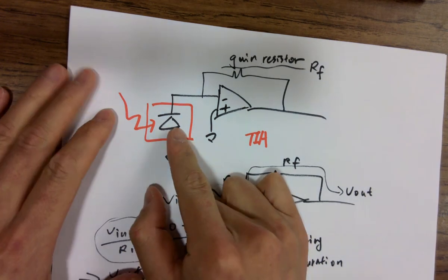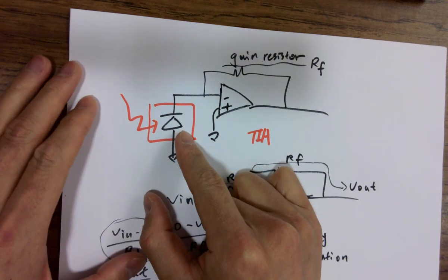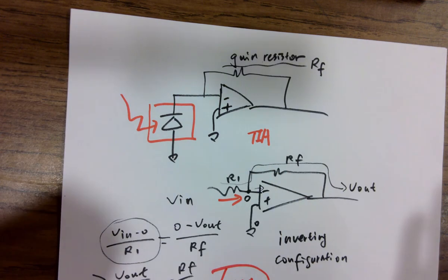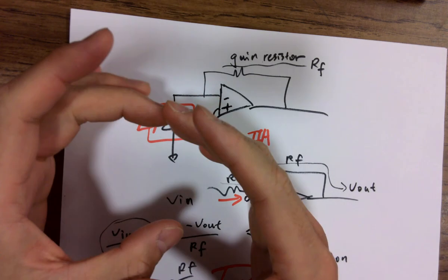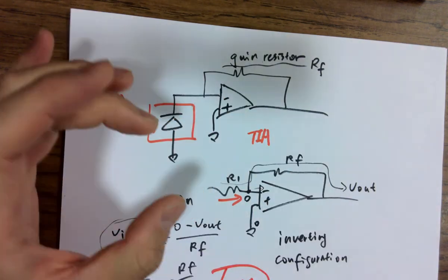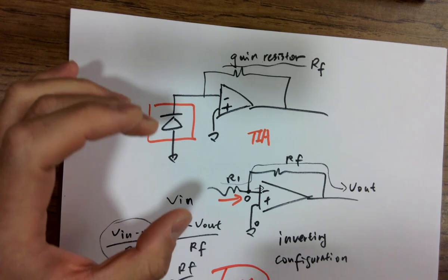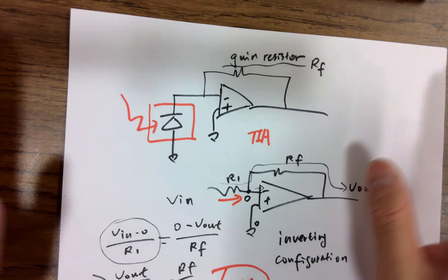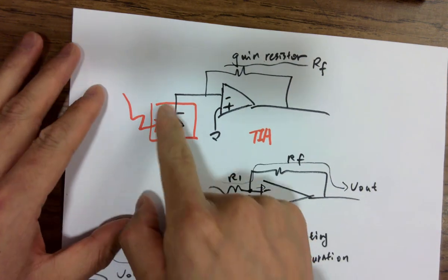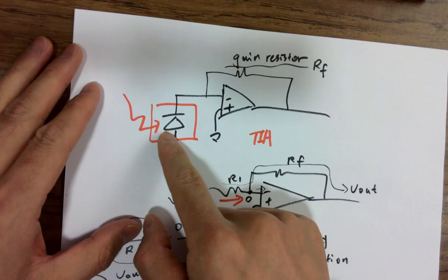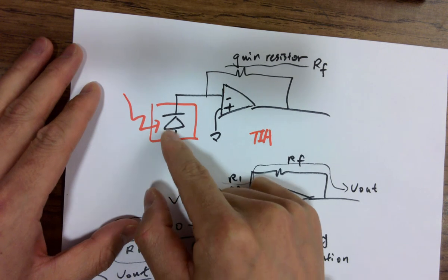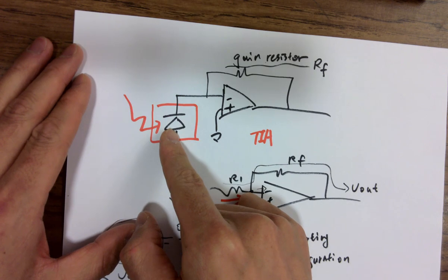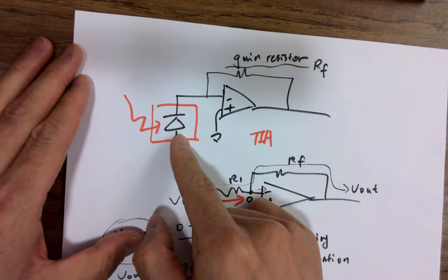So if you reverse bias a diode, it's simply a PN junction. And in that case, you have your little silicon die in your circuits. Definitely you want to open up the cover, exposing the chip, the top metal, whatever. So the chip is able to receive light through the silicon dioxide, which is transparent. This is really thin. Okay, so it receives that signal.